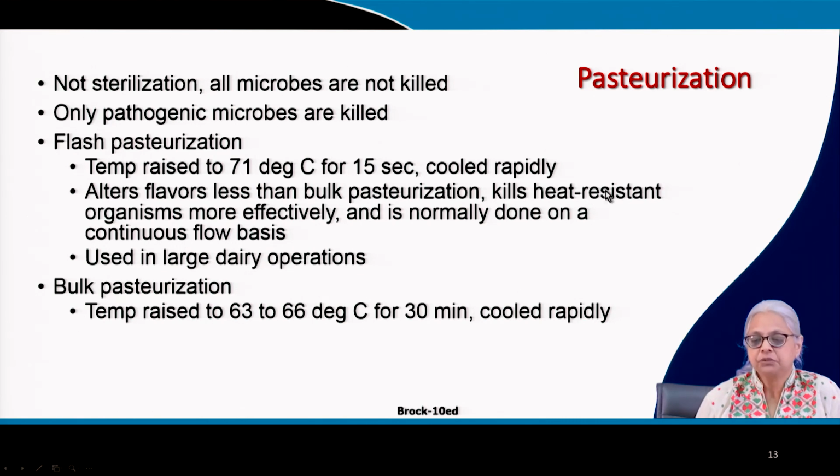It kills heat resistant organisms very effectively, and it can be done on a continuous flow basis. This is used in large dairy operations. When you have bulk pasteurization, the temperature is raised from 63 to 66 degrees centigrade for 30 minutes and then allowed to cool. This is done, again, in large operations to pasteurize large amounts of material.